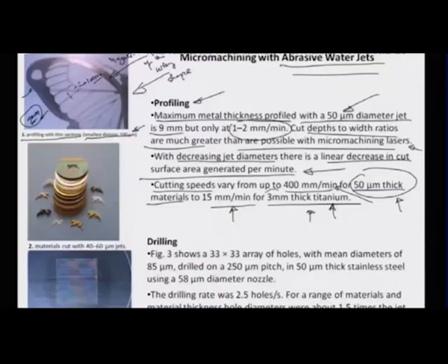As you are moving ahead you are covering more in terms of length, but the amount of depth that the jet is able to reach is lower because of the less amount of impact time that the jet would have on one particular area of the surface, and vice versa. You can see that the thickness has increased to 3 mm because of a higher cutting speed.